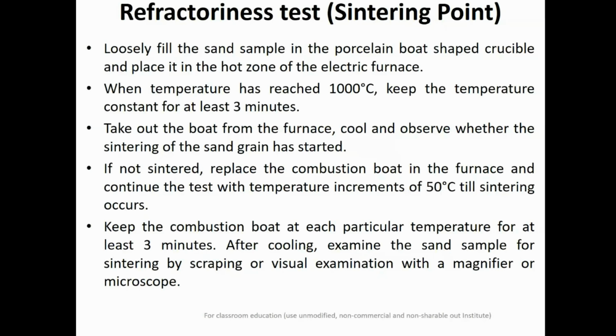What you do, you take your loosely filled sand sample in a porcelain boat-shaped crucible. So there is a crucible in the form of a boat, made of porcelain material, and then you place it in the heated zone of an electric furnace. And when the temperature has reached about 1000 degrees centigrade, you keep that temperature maintained for at least 2 to 3 minutes, and after that take the boat out of the furnace and observe the surface of that sample to find out whether the sintering has taken place or not.